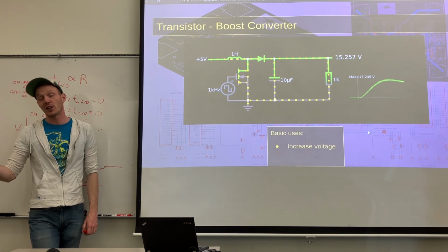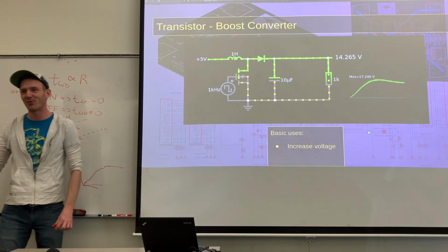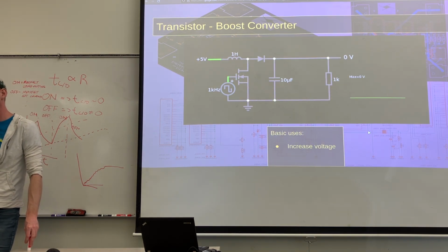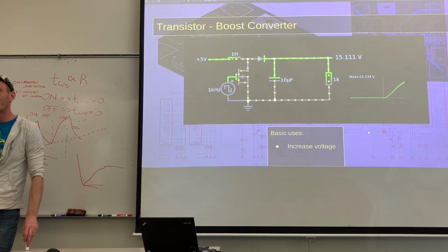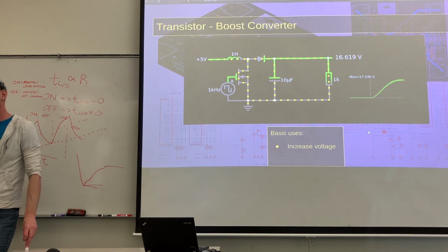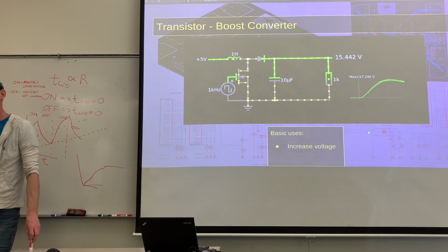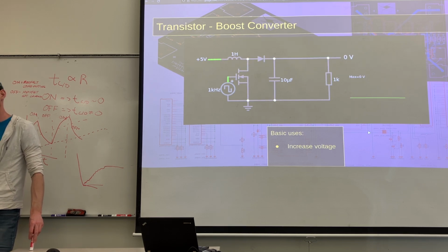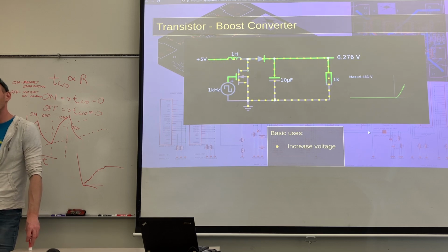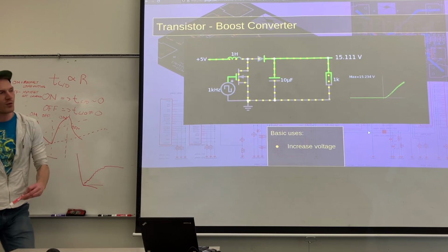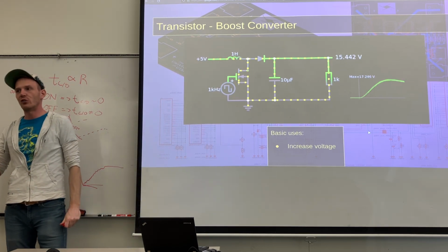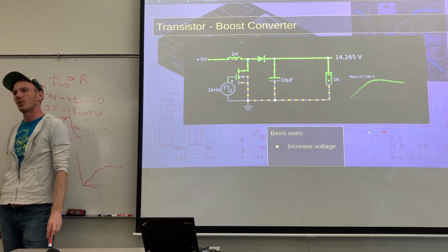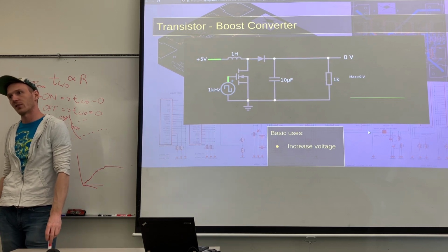terminal, it's going to get extremely hot and be painful to hold on to. The electrons want to move from this end to this end, and if you tell them that there is no resistance on the way through, they will move that way very fast, and all you will do is convert your power into heat in an incredibly rapid fashion. So every moment that this is shorted to ground, you are just losing power and converting it to heat effectively.